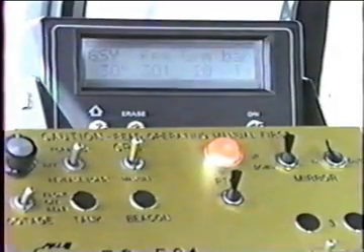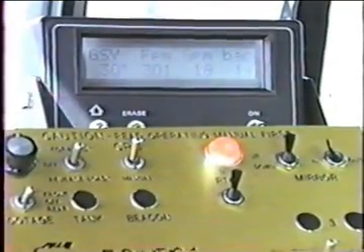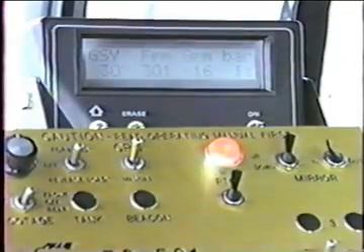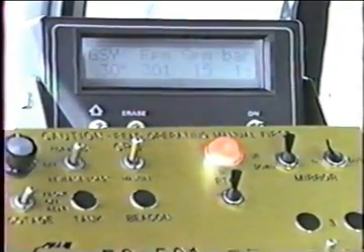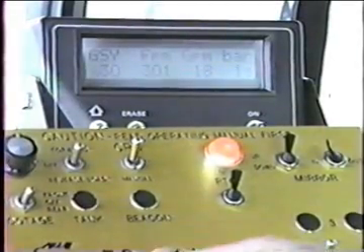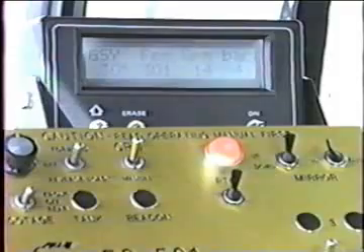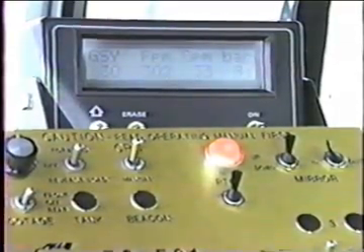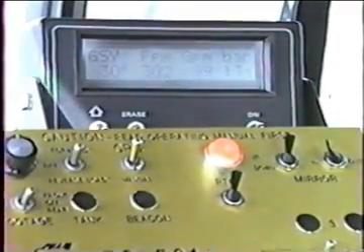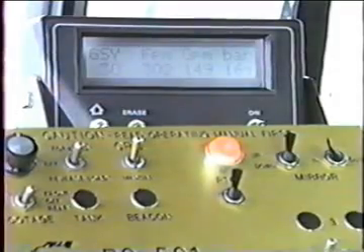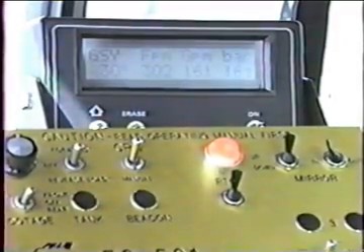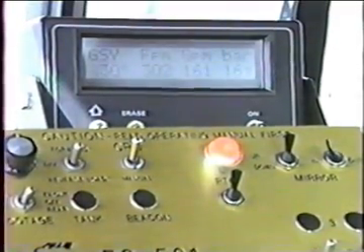We'll take it on down to 1 foot and see how we do. See if we can hold 10 gallons a minute. Again, because of the size of the gear teeth, it's having a hard time down that low. Very seldom are you going to work at that narrow of width. Going back up, you can see that the computer follows the switches right on up to full bar width. 16 feet wide, we're back at 160 gallons a minute.